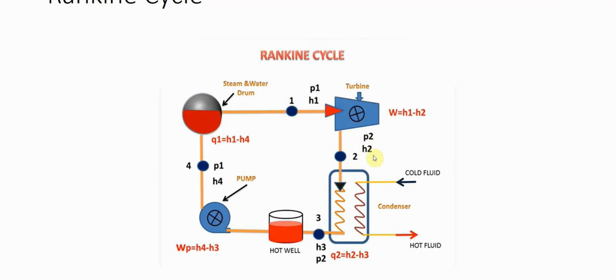And similarly the enthalpy will also increase, H2 will not be the same as H1. And the work done by the turbine will be H1 minus H2, we already discussed. Then there is a condenser, a heat exchanger, which is utilizing the cold fluid,